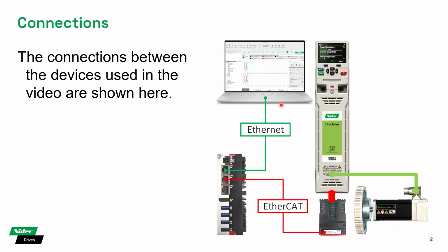So for this particular setup, we've got a laptop, we've got a Beckhoff IPC, so this is a C6025 IPC. I've configured LAN 1 for Ethernet, and then I've got a Cat6 Ethernet cable connecting my laptop all the way through to the IPC. I've then got LAN 2 configured as an EtherCAT port so that the IPC can then control our drive over EtherCAT.